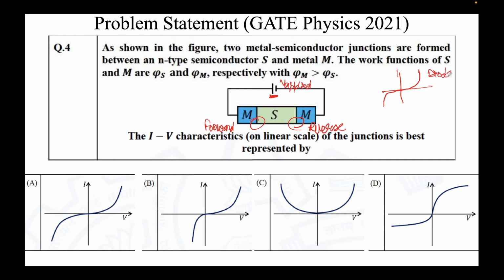However, diode 2 will be in the reverse bias side, and it would have broken down, so a huge amount of current can flow. Whatever current is provided by diode 1, or whichever is the restricting one, some current will flow. On the forward side, the combined result would be something like this.